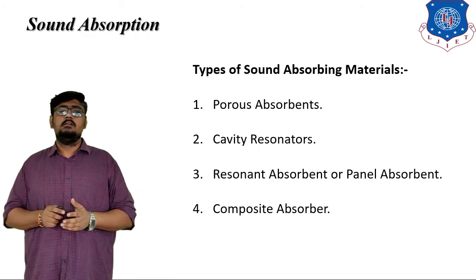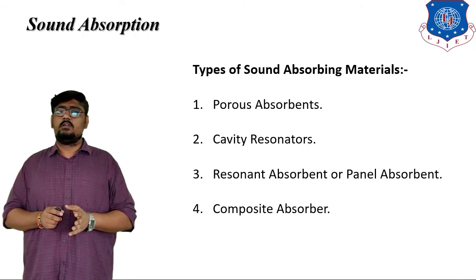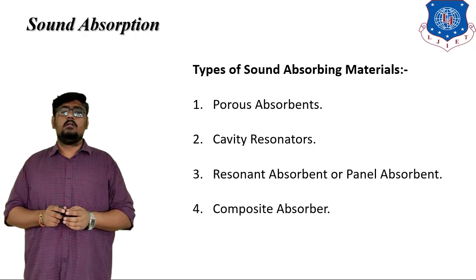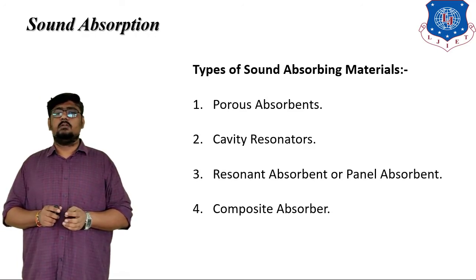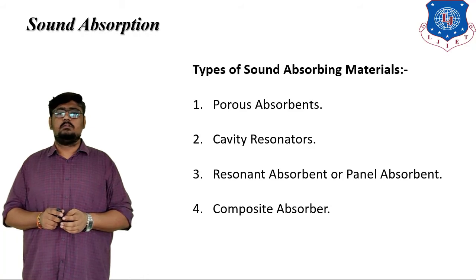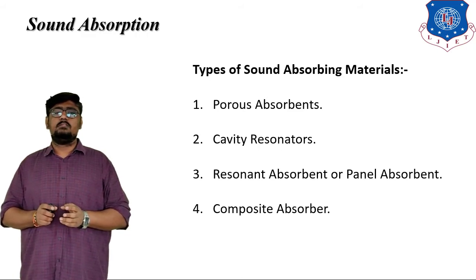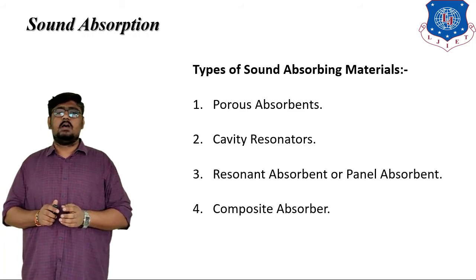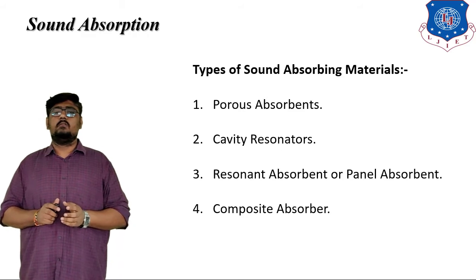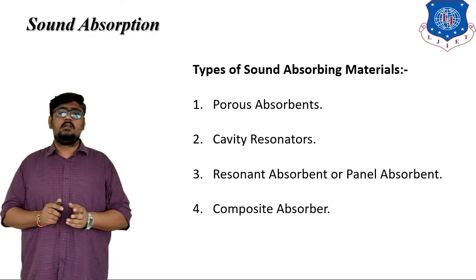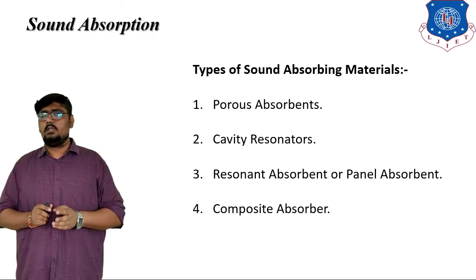A material's sound absorbing properties are expressed by the sound absorption coefficient, small a, as a function of frequency. It ranges from 0.0 to 1.0, from total reflection to total absorption. Acoustic absorption refers to the process by which a material's structure or object takes in the sound energy when sound waves are encountered, as opposed to reflecting the energy. Part of the absorbed energy is transformed into heat and a part is transmitted through the absorbing body.